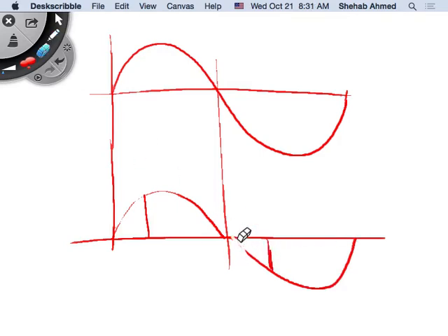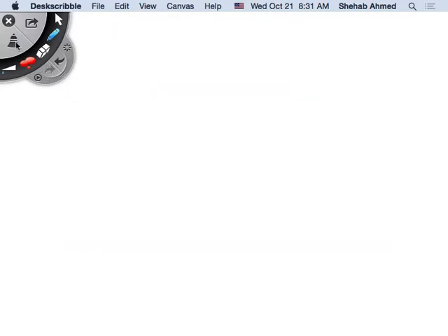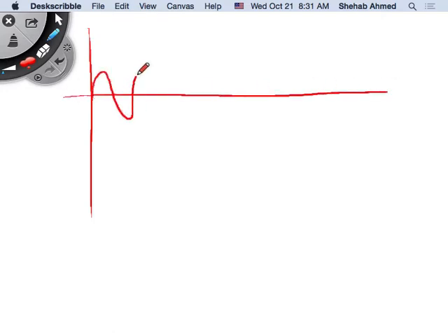I can take a part of it and apply it to my load. And this way I would have changed what? The RMS value. I can change the RMS value of current or voltage applied to the load, right? That's called phase control, meaning you are changing the firing angle of the thyristor. You're changing the phase of the firing angle of the thyristor. That's called phase control. You can also change this RMS value by doing something else. It's called integral cycle control, meaning, let's say I have 10 cycles.